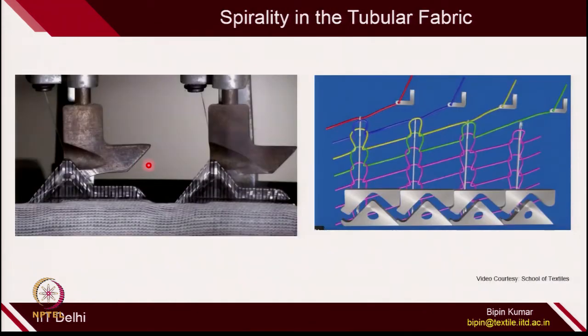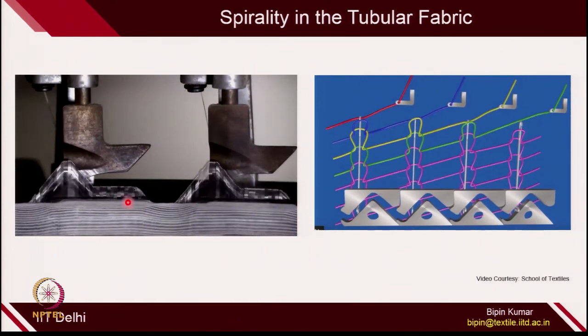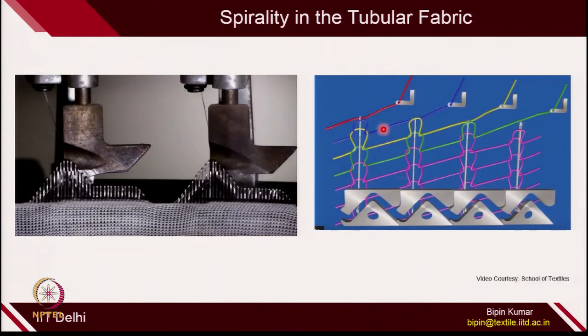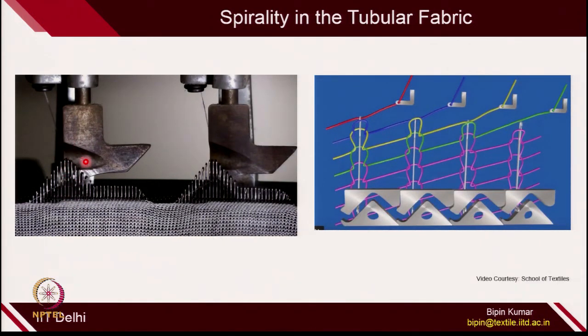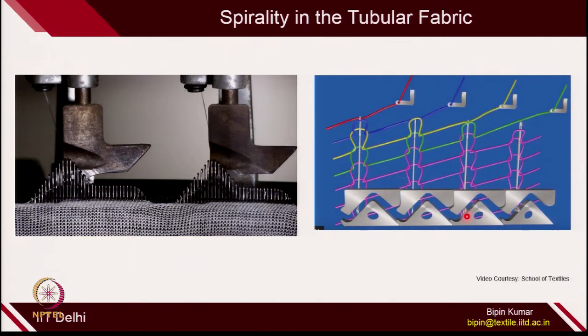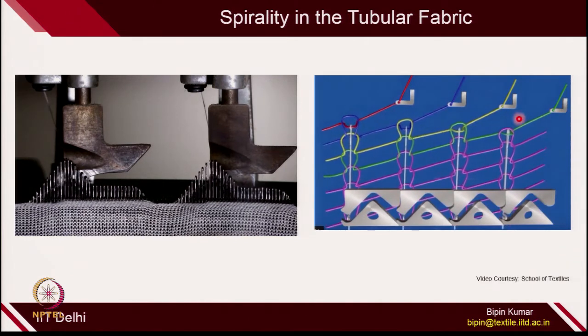How is that possible? You can see here the animations which will make it even clearer. You can see this is how the feeders are moving and the needles are making a loop every time they pass a feeder. This can be generalized here also. You can see the needles are moving and the feeder points are fixed.